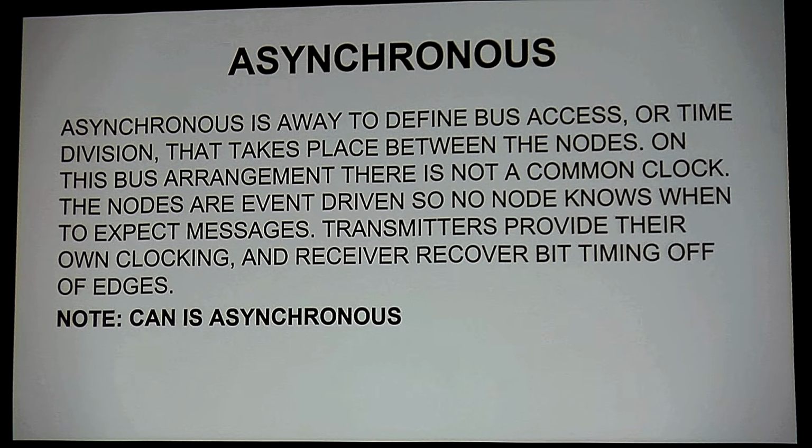Now asynchronous, this is a totally different idea. This says that every single module on the bus keeps its own time. I don't have a master. I'm not sharing a communications clock. Each one has its own clock in it. This is CAN. So I have a quartz crystal in every single node. And every node is his own master. I don't have a master-slave. Each one is his own master. And he can take communications of the bus when he needs it. It's event-driven. So this is a very different idea.